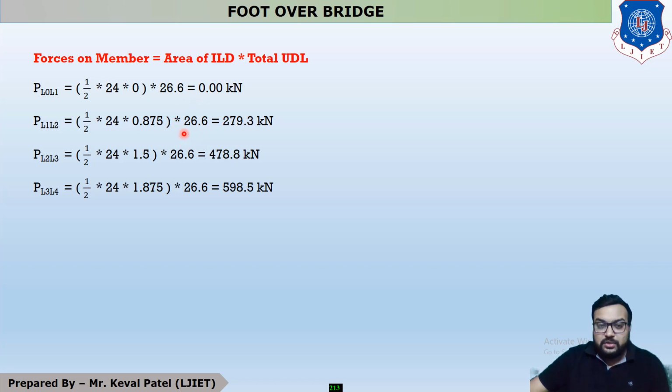So this total UDL will be found from our step number 5, in which we find the separate dead load and the separate live load, and after that we combine them into total dead load plus live load. It is already discussed that there are two members, first one vertical and second one diagonal, having some portion in tension and another portion in compression. So whenever we design the vertical member and diagonal member, we have to calculate separate dead load and separate live load.